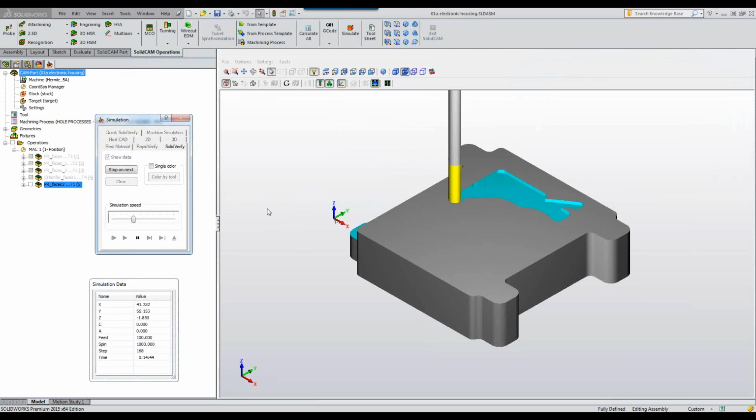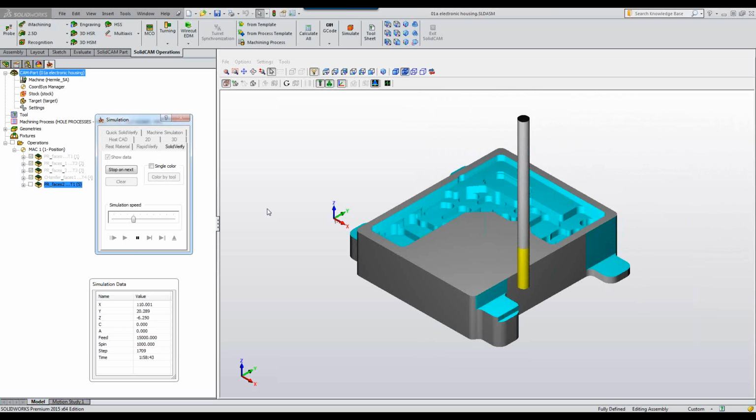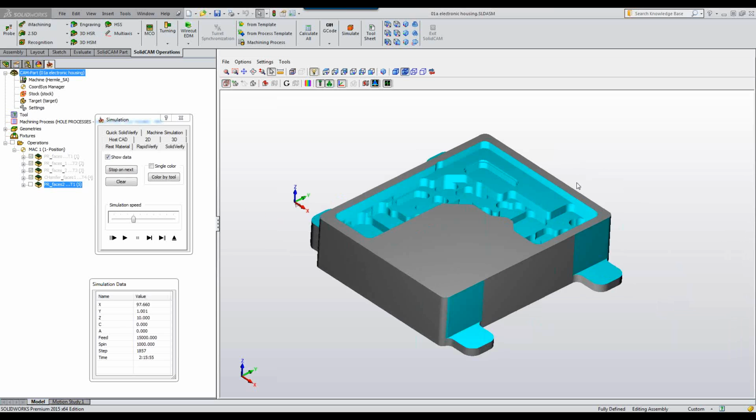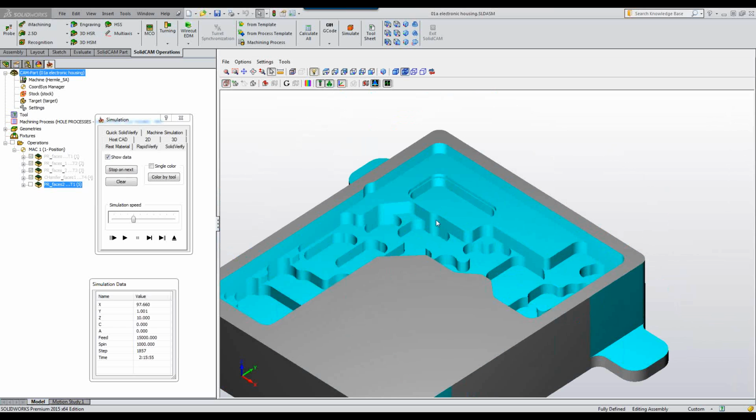And again, you can see it's machining all of the areas that I wanted it to machine. But obviously, the areas where this tool is too large to go into, it will not work in those areas, as shown over here. Okay? You can see there's a lot of areas in this part over here that was still not machined because this particular tool was not able to enter those areas itself. But you'll note also where it did work, it picked up those edges over there, as shown over here, the different levels. All of this was automatically picked up. Okay.